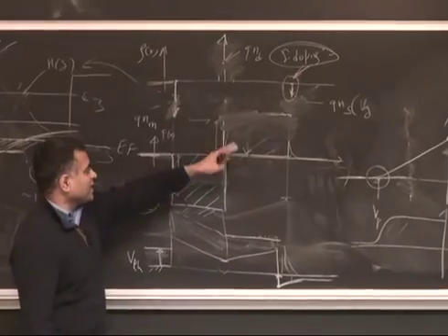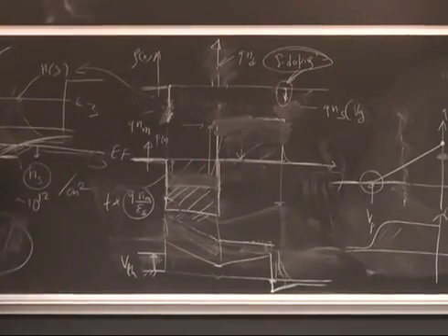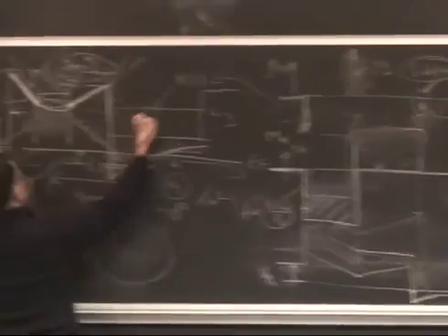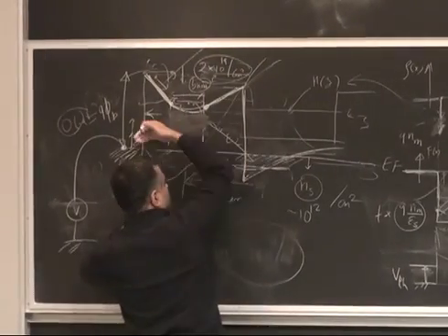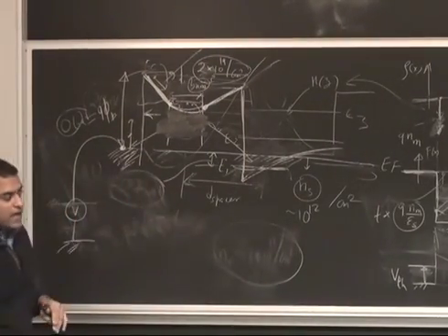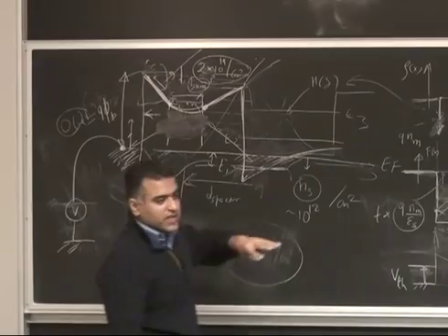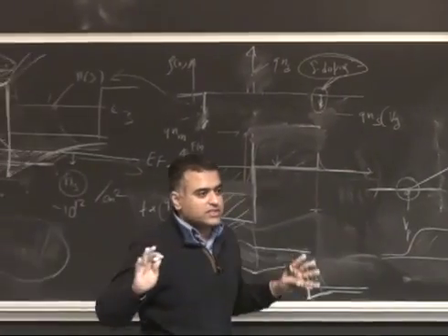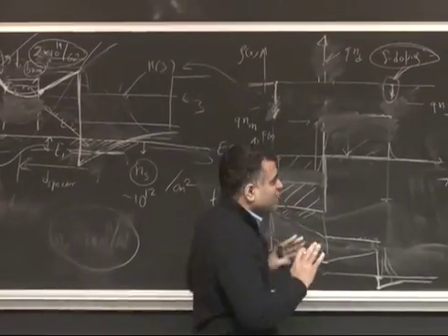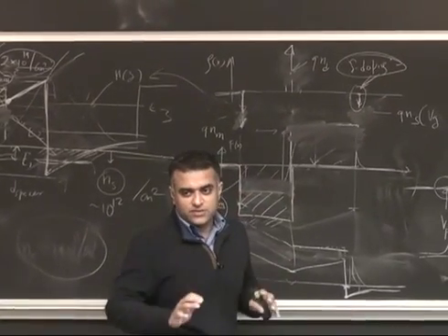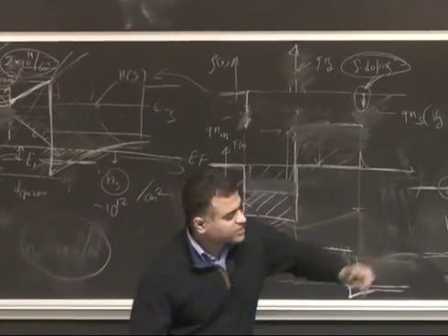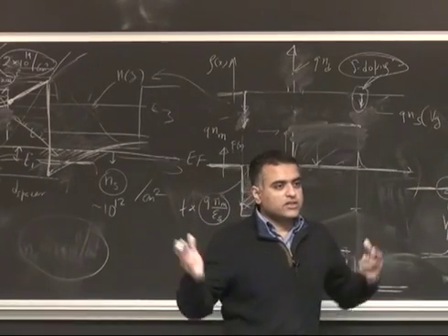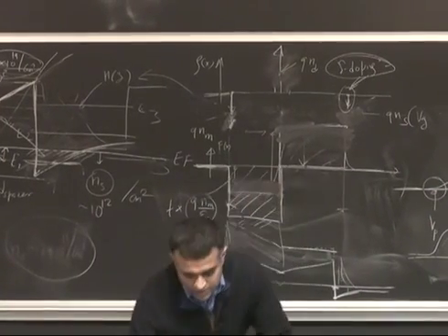Because basically what happens in reality is when you forward bias this and you pull it down, your current turns on. It's a Schottky diode. Your current kind of turns on. And 1D Poisson is not meant for transport. It's meant for electrostatics primarily, near equilibrium situations, or when you're pinching it off. But on states, it doesn't like that. That's a limitation of this program. There are obviously a lot of other programs which you can use to see what happens.